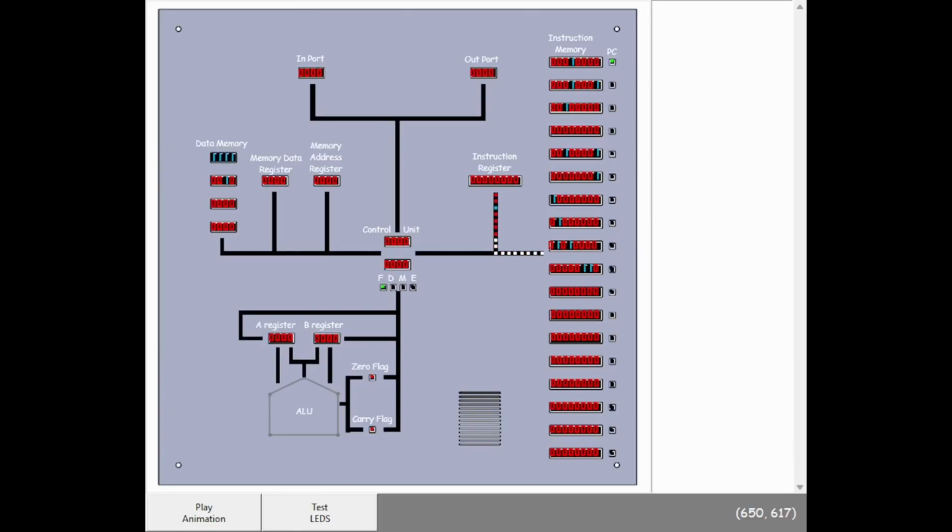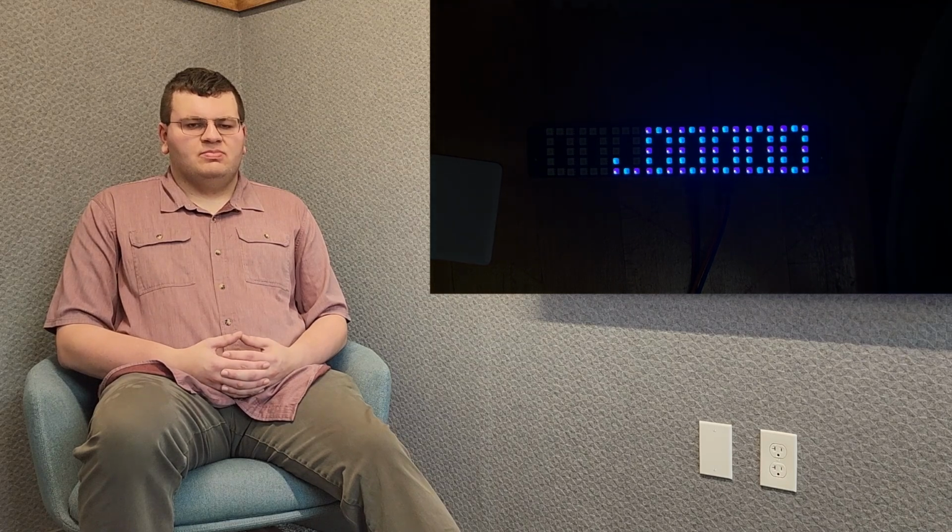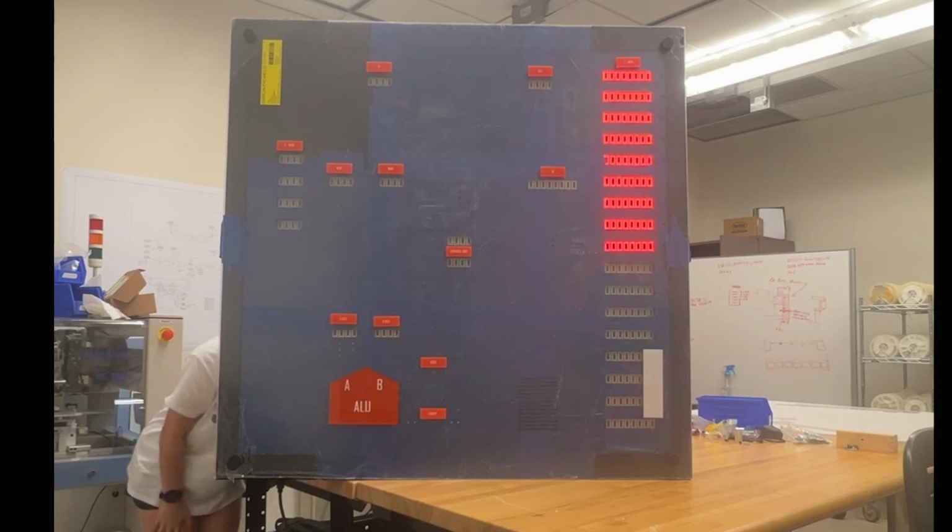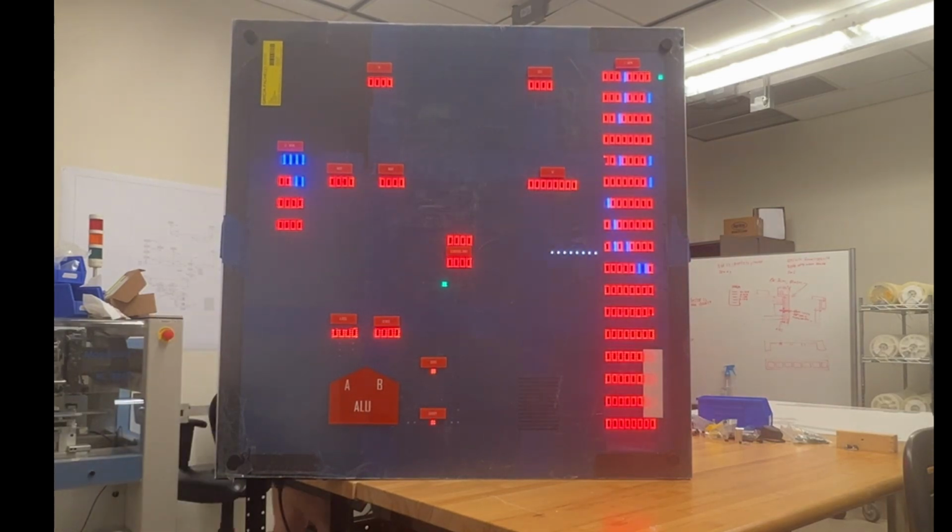In order to be able to control the model, we ended up creating a Python tool that could utilize actual C code that we would later use on the model. This allows us to develop the code without the need of physical hardware. Once we ported it over to the system, we used the ESP32's inbuilt LED strip library. This allows us complete control over any LED in a strip, allows us to set it to whatever RGB color we want it to. This animation starts by loading the program with default values and then begins to run.